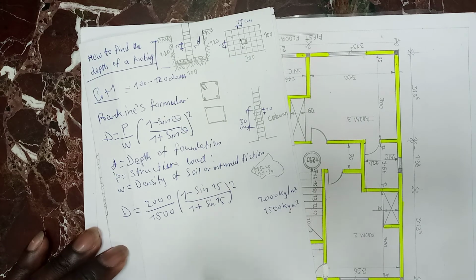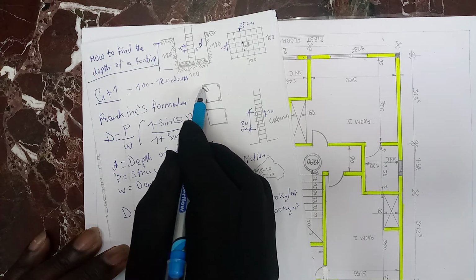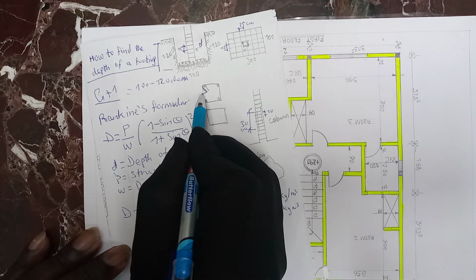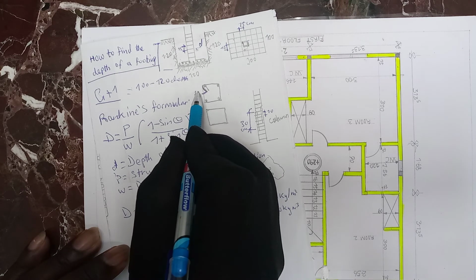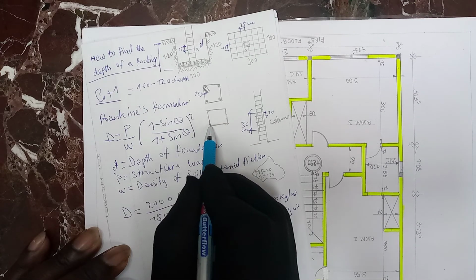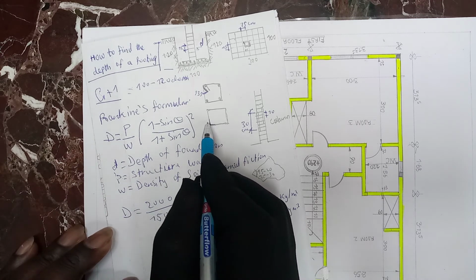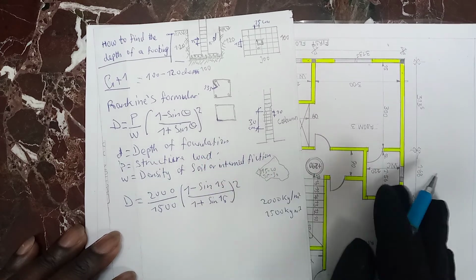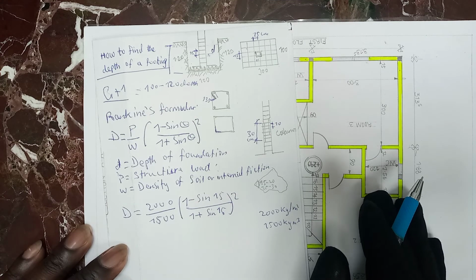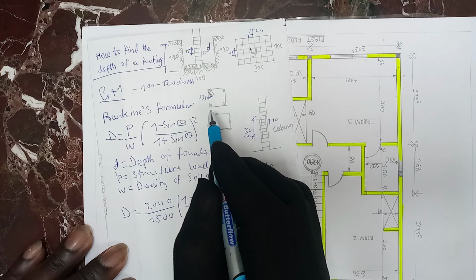And guys, do not forget, this is your stirrups, and this is the hook. The angle of your hook must be 135 degrees, and this one that is just 90 degrees can easily open when it is being loaded, when there is bending moment or shear force.